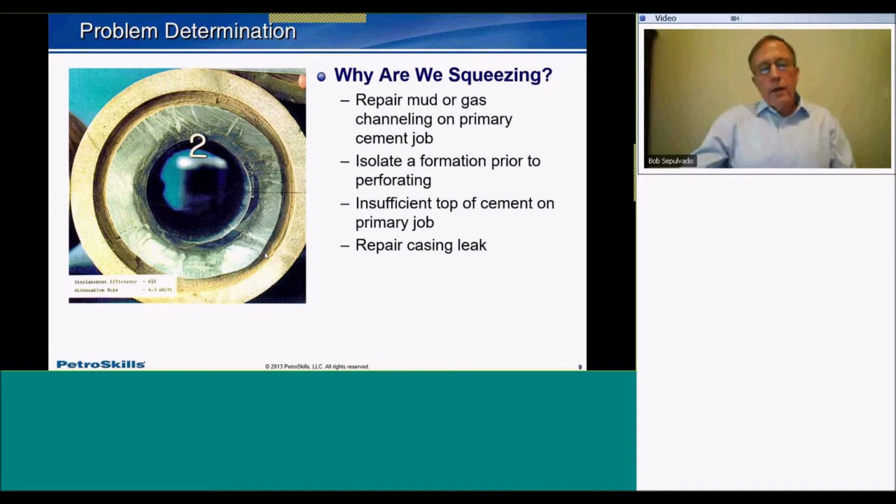So one of the things, when we go to run a CBL, cement bond log, those of you who are familiar with cement bond logs, it has a transmitter and 2 receivers, 3 and 5 feet from the transmitter. It emits an echo from the transmitter, and it hits the casing, and then it resonates down and is picked up in terms of microseconds in the receivers. When you have no cement around the casing, what you're going to hear is almost like a sonar ping sound, and the sound's going to resonate very quickly and be picked up at the receivers. And also on the amplitude curve, you're going to have very high positives and very high negatives. Now, a casing that is encased with cement behind it like this, instead of a ping when it hits, it's going to be more like a thud.